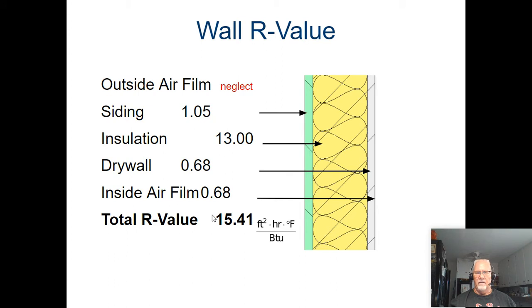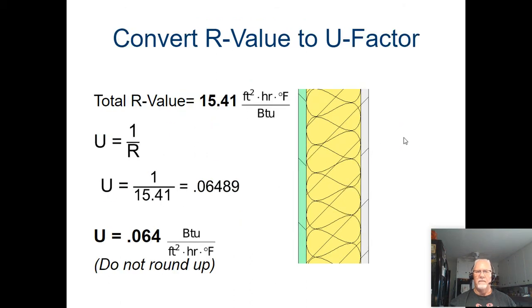It may be a little tedious in some cases because you have to figure out each of these layers of the wall. But once we've broken that down, as we have in our Revit drawing of our shed, it's easy to figure out each layer, from the siding on. On this one we don't even have the OSB layer. Once we have the R value, we can calculate the U factor, which is what we'll use in our heat transfer formula.